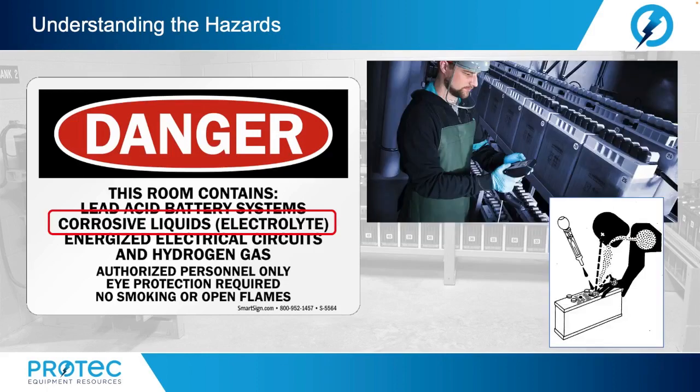Now, when working on lead-acid batteries, wearing a face shield and plastic or rubber aprons and gloves is required to avoid chemical burns from the sulfuric acid. Also, exercise caution breathing around lead-acid batteries if there is poor air circulation and ventilation. Lead-acid batteries can generate toxic gases such as arsine and stibine gas.